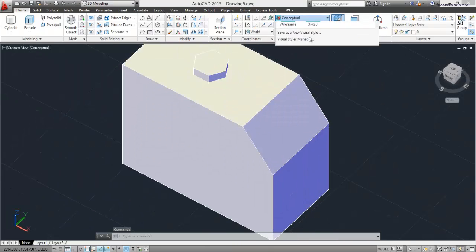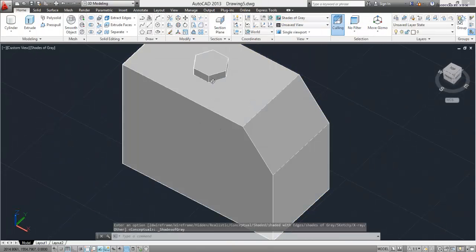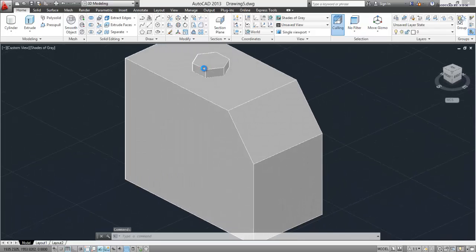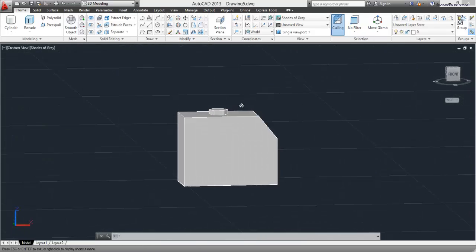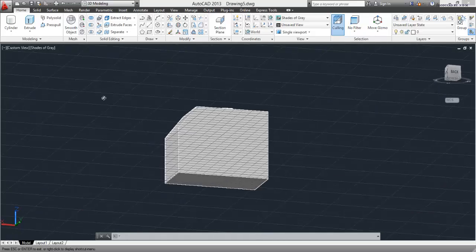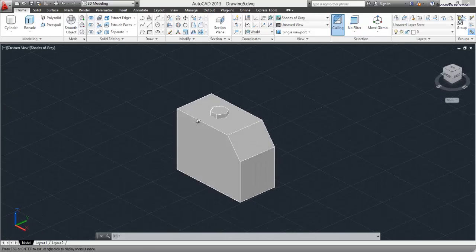3D modeling can be a useful graphical tool in helping us visualize our designs. Primitives can be combined to form more complex geometry, or we can simply draw closed profiles in the XY plane and extrude them using the press pull command.